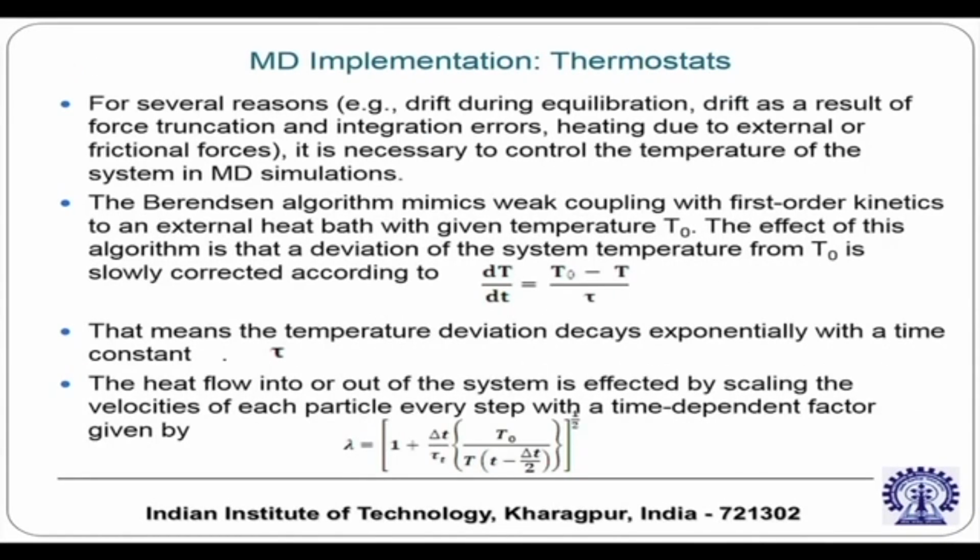The next concept is a very important concept if you are implementing an isothermal problem: thermostats. For several reasons, for example drift during equilibration, drift as a result of force truncation and integration errors, and heating due to external or frictional forces, it is necessary to control the temperature of the system in molecular dynamics simulations. So you have different algorithms which bring the temperature back to the original temperature, which has artificially shifted from its value for a problem which is actually an isothermal problem.